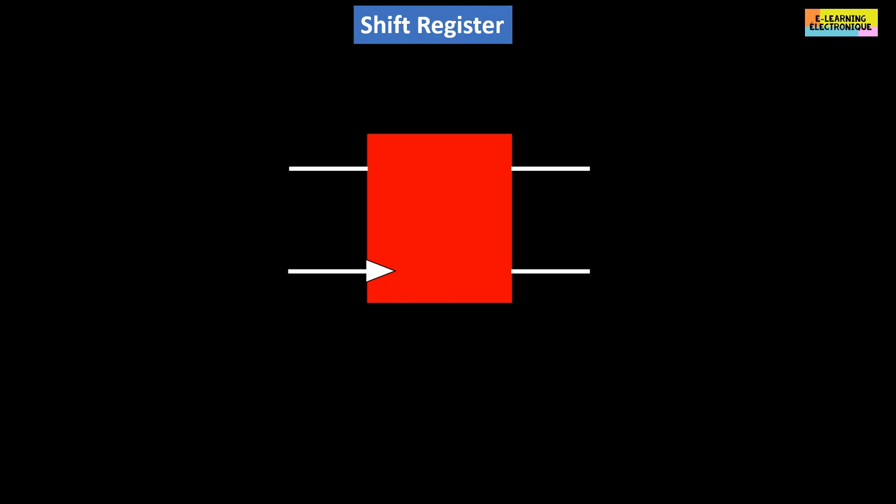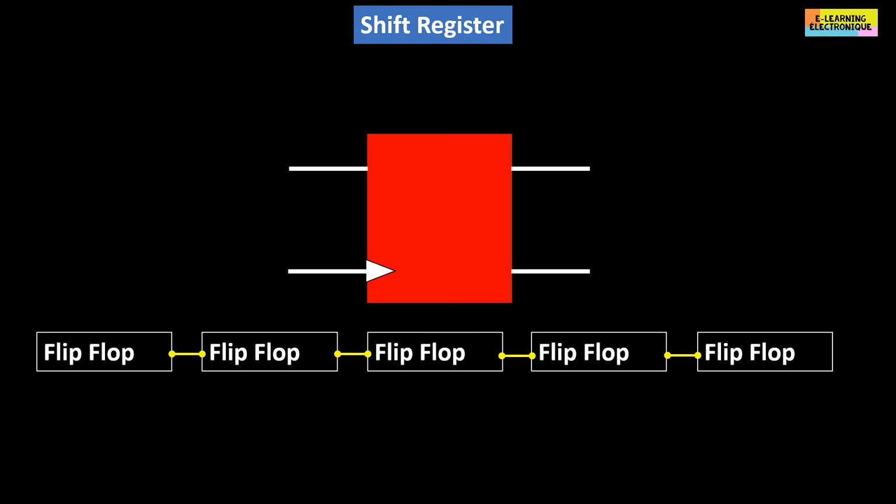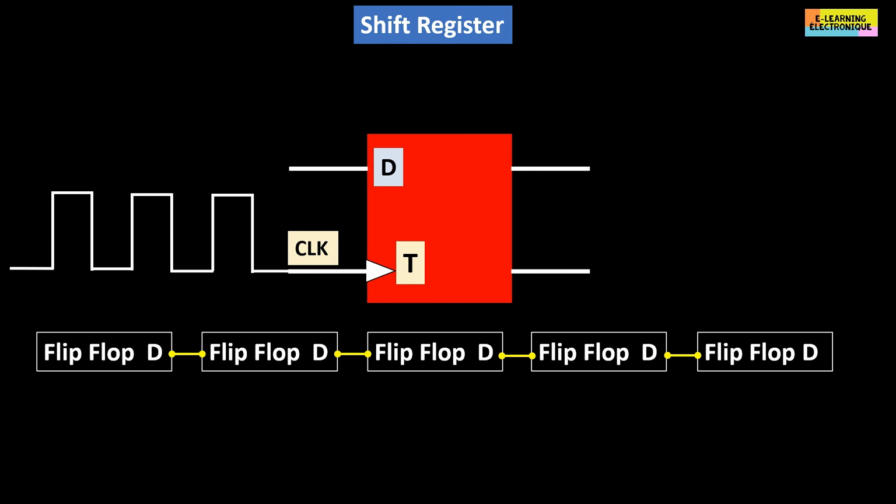The shift register is an assembly of several electronic devices called flip-flops. There are several models. Here the D flip-flop will be used. It has two inputs. A first input for the data named D, like data, and a second input, T, for the time, controlled by a clock signal. The D flip-flop has two complementary outputs, one called Q, and the other Q bar, which takes the inverse value of Q. The operation is relatively simple.